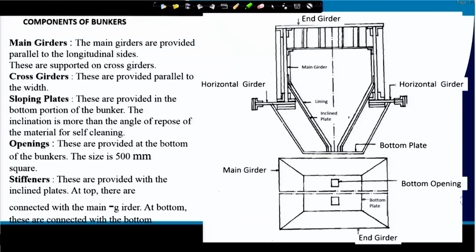It will receive the material from the top and you will be evacuating either from the bottom, or if you have a flat ground mounted surface, you can use another reclaimer machine for reclaiming from the bunkers. In most of the bunkers, you will find a hopper portion at the bottom, with a gate, and from there it can be taken out.